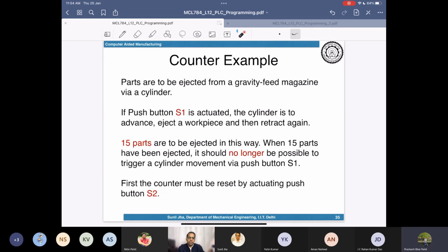So you have this kind of power with the supervisor that unless he presses S2, he cannot continue the operation for the next cycle. The operator can eject 15 parts, then the supervisor has to give one input through S2. Then again, the operator will continue with another 15 parts, and so the cycle goes. So every time after 15 parts, it requires some intervention to control the operation, how many cartons are being prepared or how many objects are being packed like this.